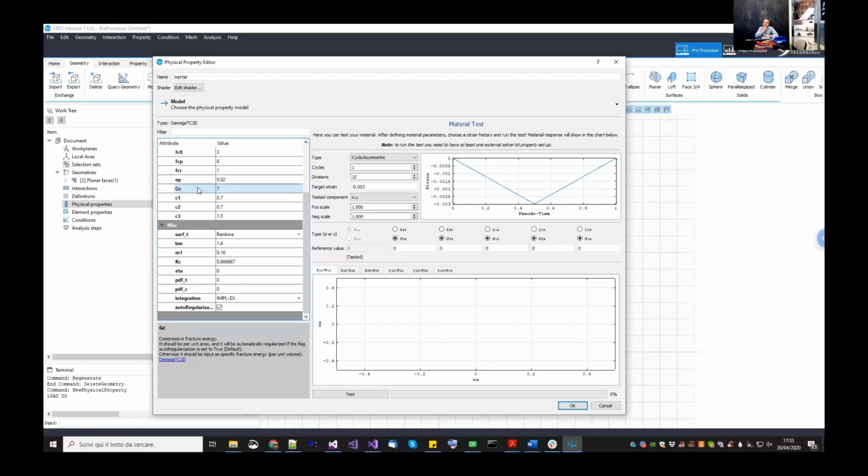Actually, this is very fine when you do micromodeling, because in this example, we are going to mesh it with a mesh size of 10, which is exactly the thickness of the mortar, okay? And the element is perfectly regular. It's a quadrilateral element with all the sides equal, so it doesn't make any difference. But let's say you want to model a very large model.